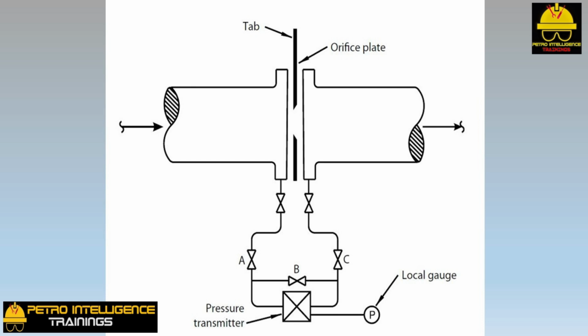Now solve for V. 5. Look at the tab sticking out of the orifice flanges. Look at the picture. If the orifice plate is installed in the correct direction, there will be a number stamped onto the tab, toward the flow. This is the orifice plate hole diameter. For example, if you see 0.374 stamped on the tab, as shown in the picture, the orifice hole diameter should be 0.374 inch. 6. Using the hole diameter, calculate the volume of fluid.